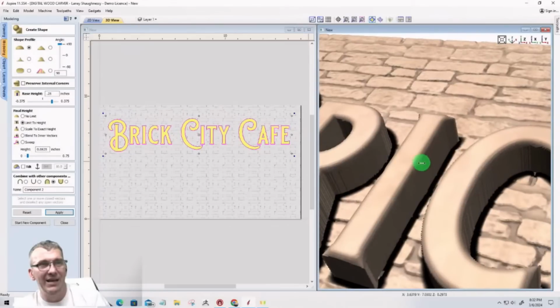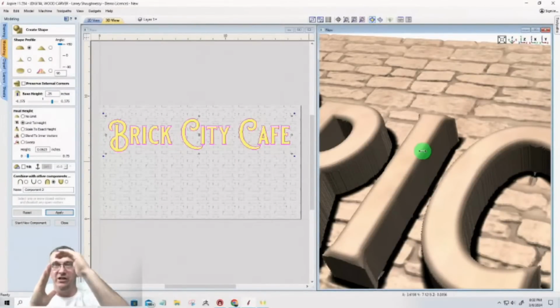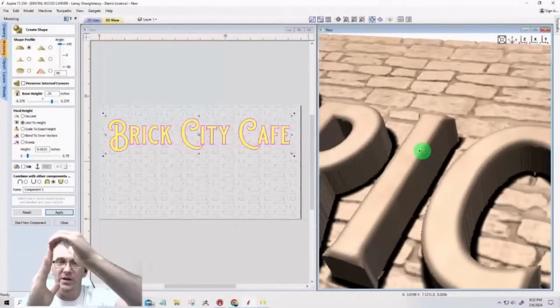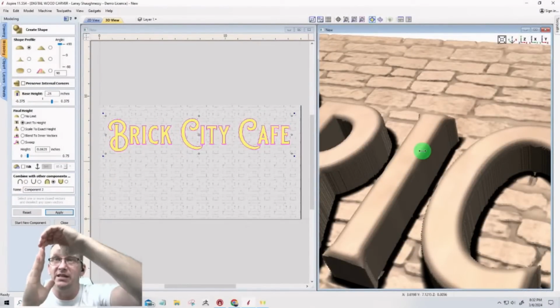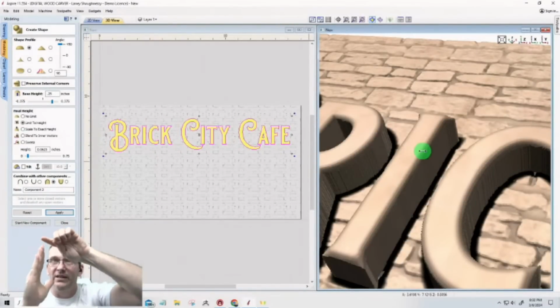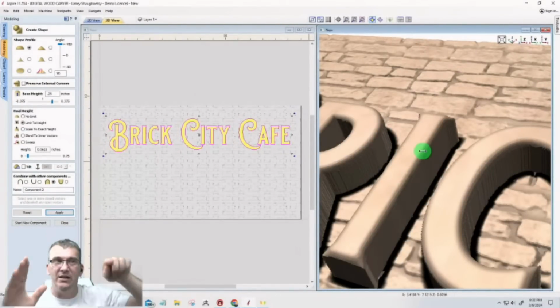And then the shape height after the 1/4 of an inch, now the shape is going to start, right? So the 1/4 of an inch is the base height. That's the straight wood. Now my dome is going to get built on top of that. But my dome, instead of going the full 90 degrees, is only going up a 1/16 of an inch, and then it's flattening off across the top.